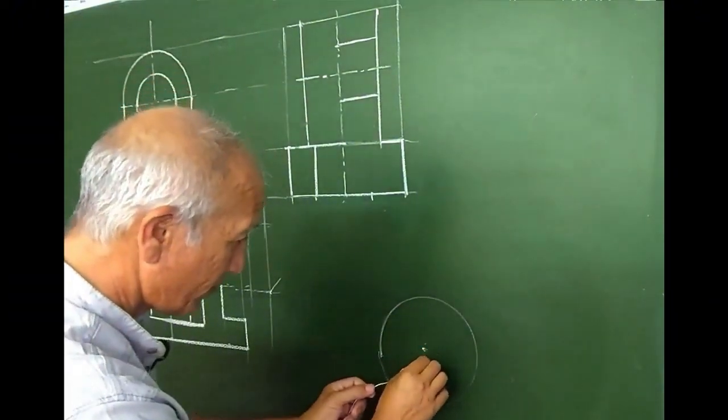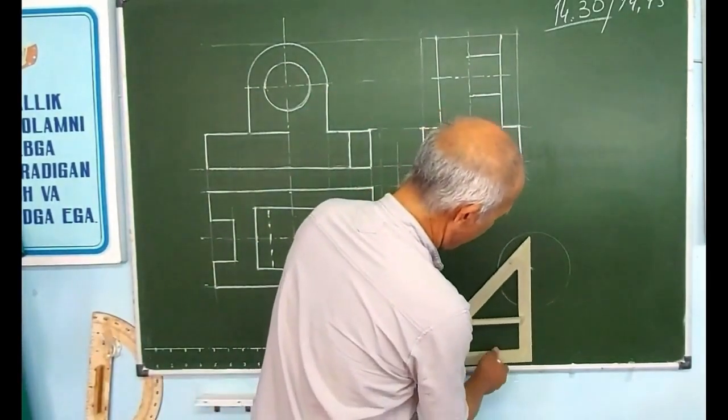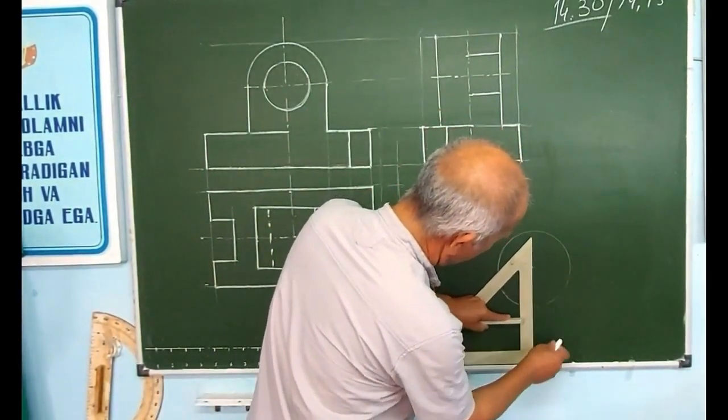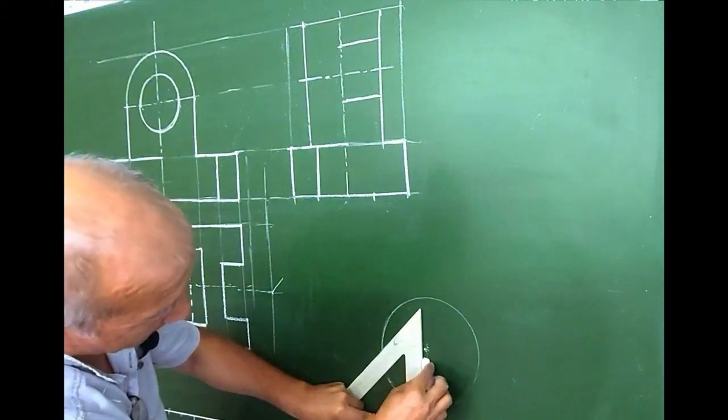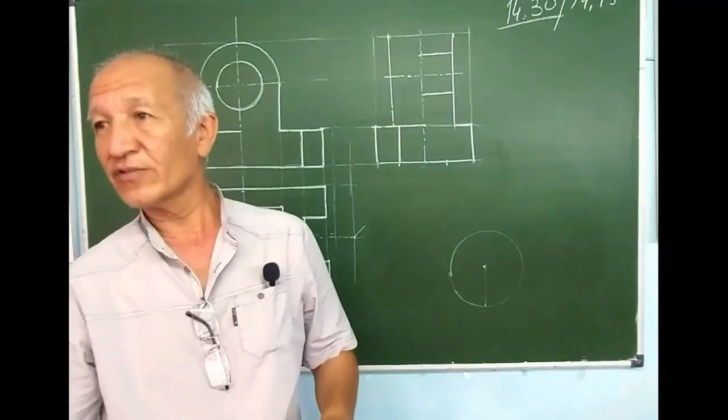It needs to line up straight from here. This line here needs to be straight. It should be straight like this. Some people don't align the axis properly like this. They don't take the axis straight and just place it carelessly like this. If you do it this way, the isometric axis will be off and distorted.